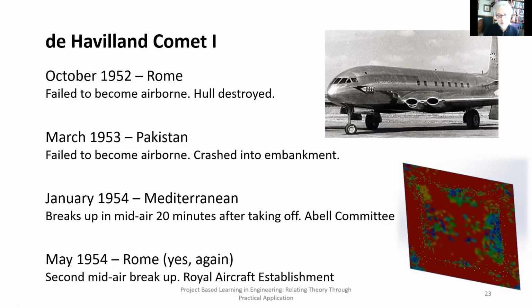And one of my students, she wanted to investigate what happened there. And so she modeled that fuselage, and she looked at stress concentration of these corners of the windows and saw that there are cracks that propagate. And so she did a statistical analysis, created a model, did the statistics on it, and got some mean values and standard deviation of failure in terms of how many landings and how many starts. And then we went back and looked at these cases here. I mean, she was right smack in the middle of what actually happened. So that was instant reward.